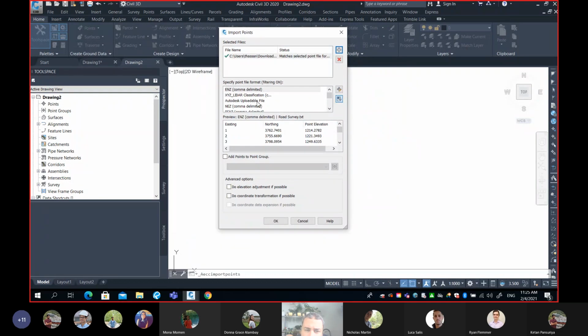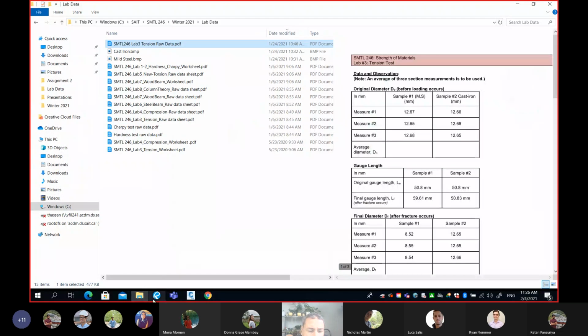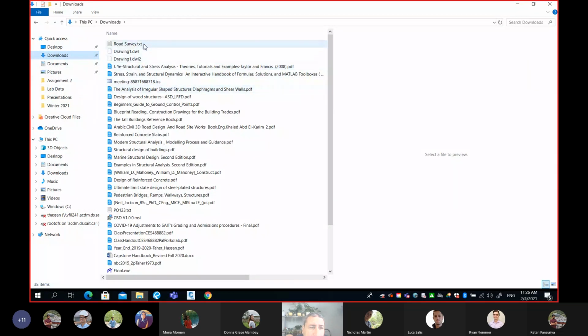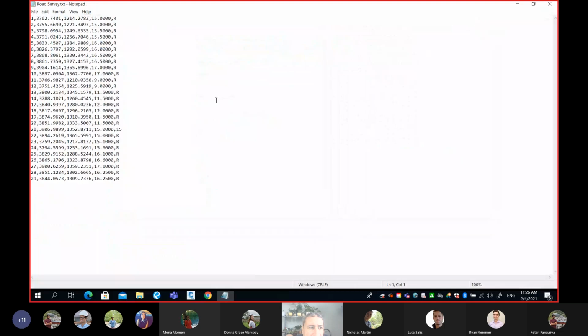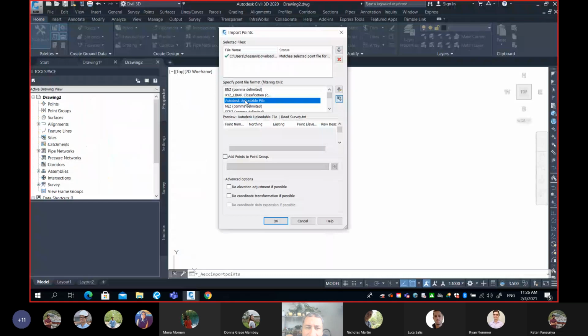You need to check the format. So I'm telling you right now the format, which is not a secret. If you take your time and simply look at where I downloaded, it's here in downloads, and you go to road survey. Watch this. What you see here is the road survey data, which is point number, easting, northing, elevation, and description. So close this one here. We know the format. I'll come back here and I'll say PENZD. This one here: point number, easting, northing, elevation, and description.